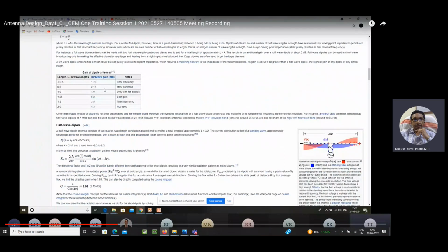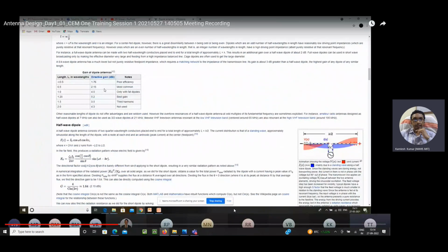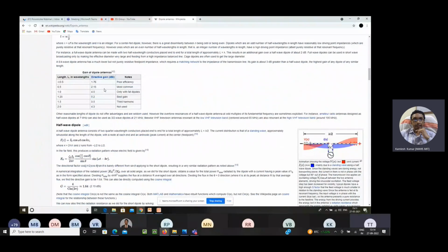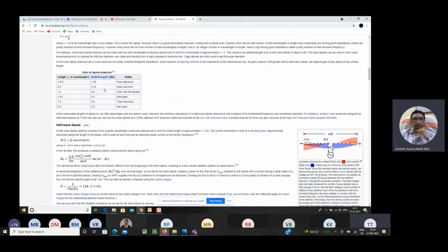And then, in order to give the excitation, there should be a transmission line with some bend. It has to accept the characteristic impedance of 50 ohms. One of the important concepts in antenna theory is that only if there is proper antenna matching can the proper signal be sent out. If there is no proper matching, the complete signal will get reflected back and you will get a return loss. So these are all the things we have to analyze and take into consideration.